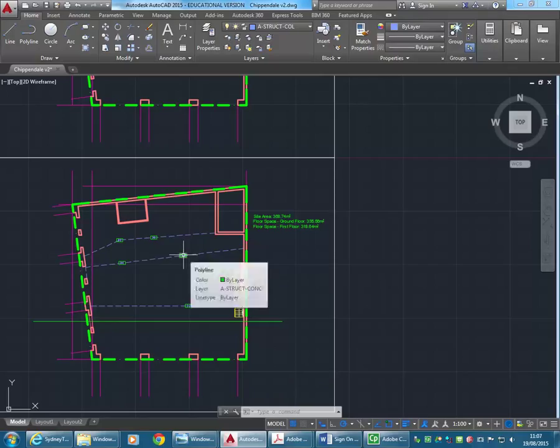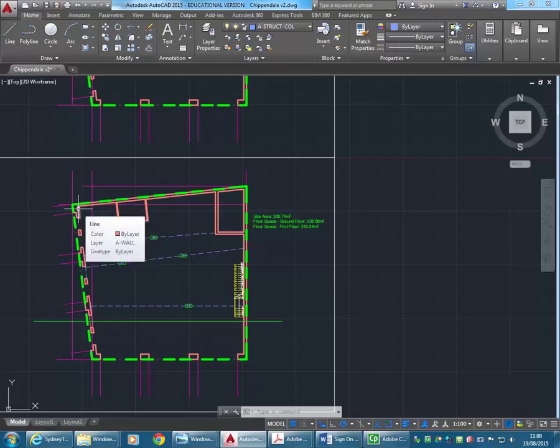The reason it's reflected is that technically, if it was a true ceiling plan, it would be a mirror image of the floor plan because you're cutting and then looking up. But with a reflected ceiling plan, you cut the walls in the same direction as a floor plan, so it should look basically the same. It might be cut at a higher level, but it should be oriented the same way. But then it's as though you've got a mirror on the floor reflecting what you would see above. Again, it sounds complicated when you describe it, but to draw it is much, much easier.